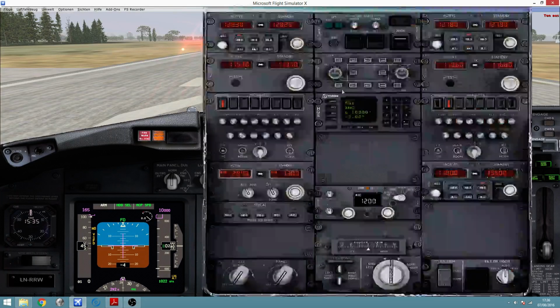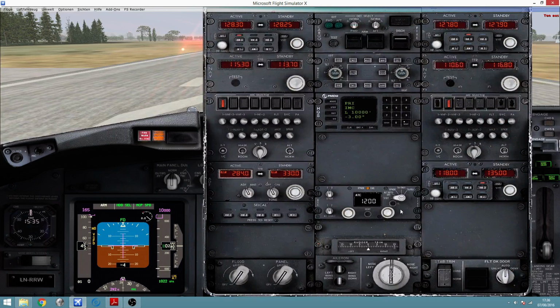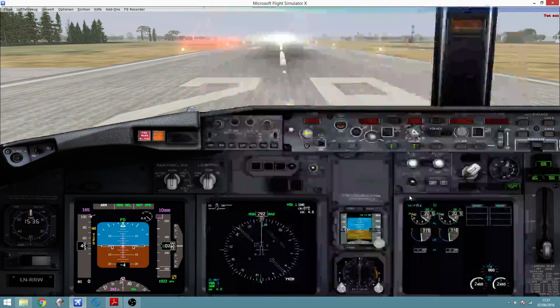Well, I click on Shift 4 and here I have a transponder code. Remember that this is something that we've seen in our surveillance chapter. This is the code assigned by the air traffic control so that they can see us on their screens. Let's assume that the air traffic controller gave us 4303 as the code. And we select this, which is the TCAS, to TARA, Traffic Advisory Resolution Advisory. Well, this is just in case we meet other aircraft, to have the TCAS active. Good.